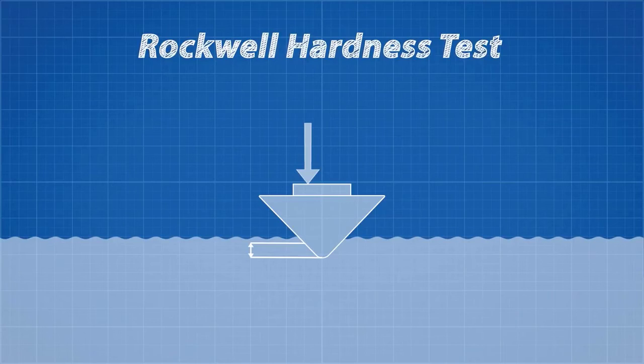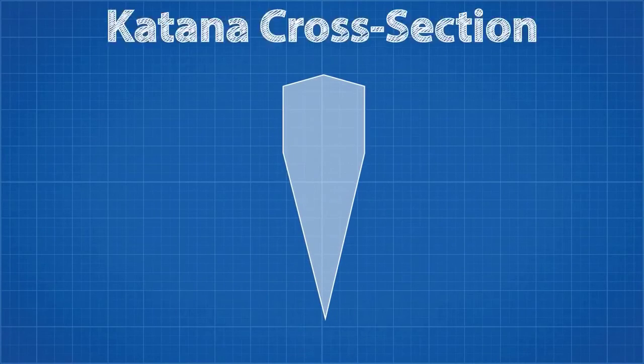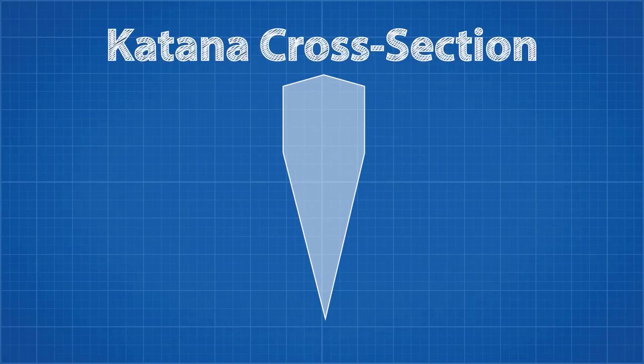Diamond is a very hard material, which is why it is used in cutting tools. One of the fantastic properties of steel is its ability to be heat treated, to have its hardness tailored in different areas. For example, with swords you want your cutting edge to be hard, but the core of the blade to be ductile. This means the sword can bend under pressure without breaking, while the cutting edge can resist damage,